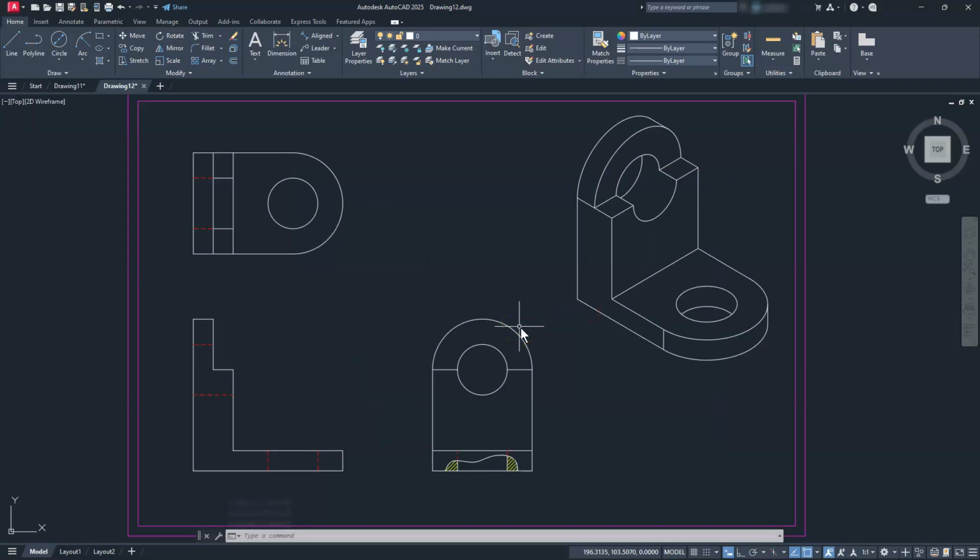Next thing I like to do is go ahead and start putting in my center marks, right? So with that being said, I have to determine what my extension is going to be off of that. By default, I think the extension is like 0.18, which is super duper small. Remember that these lines going across is at 50, so 0.18 I won't be able to see, so I'm going to adjust that number to either 3 or 5, which is what I typically like to use. So I'm going to type in center EXE command, hit enter, and then I'll type in 3, enter, right? Nothing really changes or happens, but you will see that here in a second.